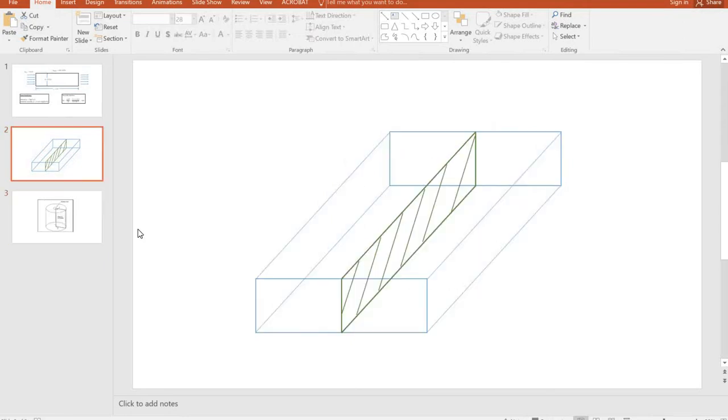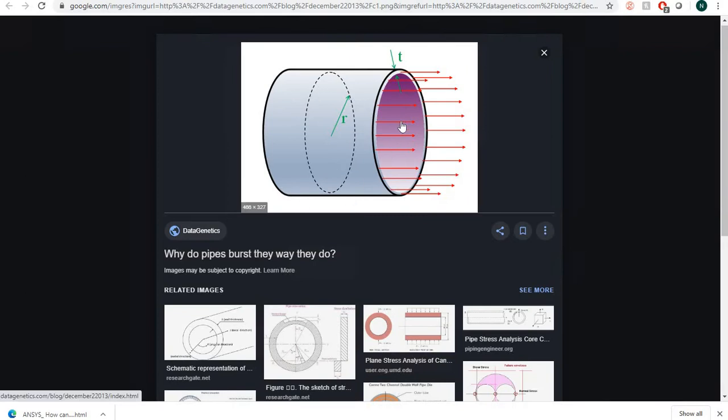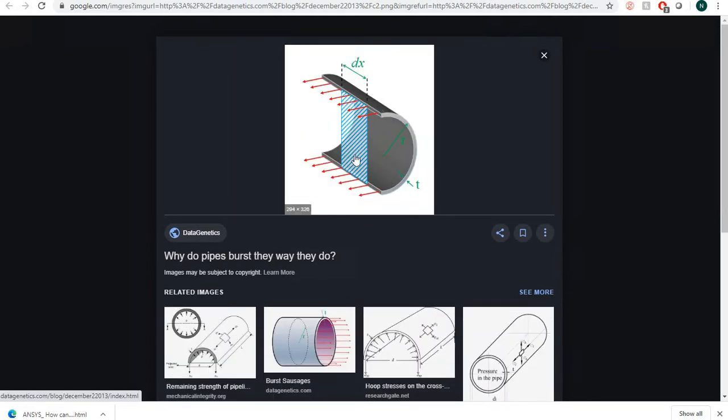But imagine you have a circular pipe like that. If you take a cross section in the middle like this, it should have quite a good influence from the side wall as well, because this is curved. Near the top part, there will be resistance to the flow, shear stress acting on this cross-sectional area, and the flow will change. You may see similar behavior in certain conditions, but it should be completely different. It may show the correct flow behavior, but if you want to analyze the pressure, the temperature, the properties, they will deviate up to a certain point.